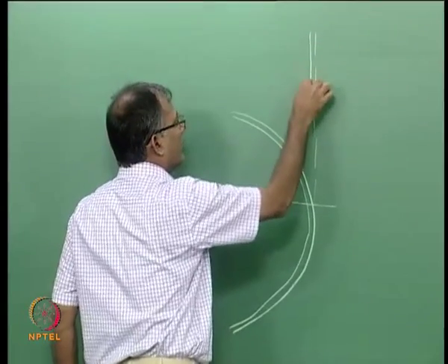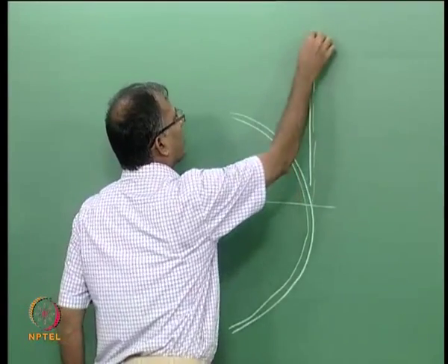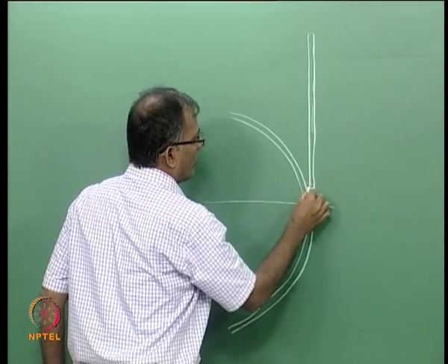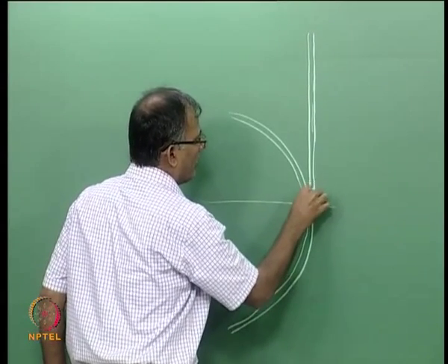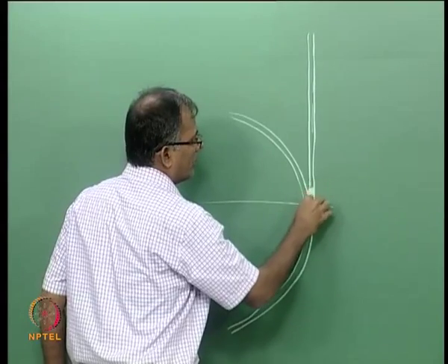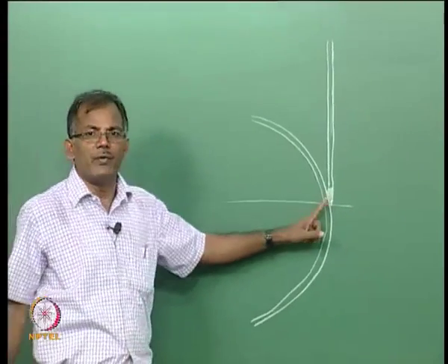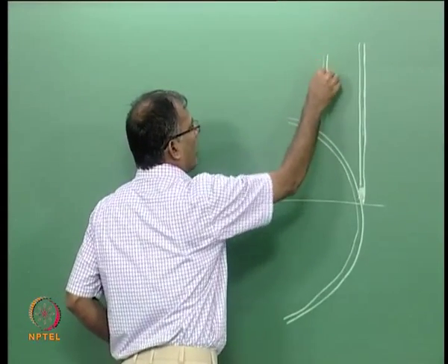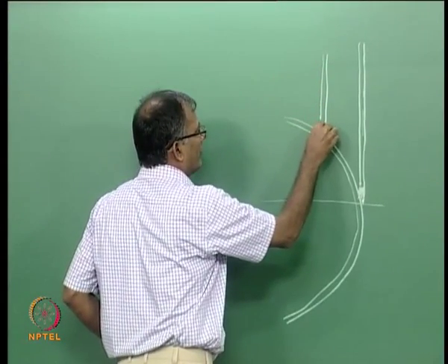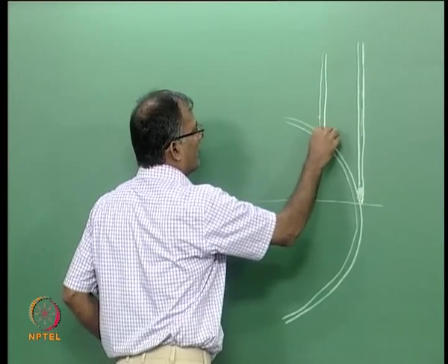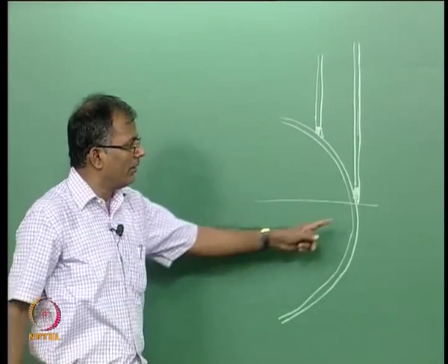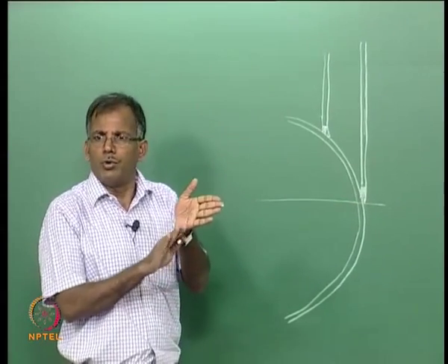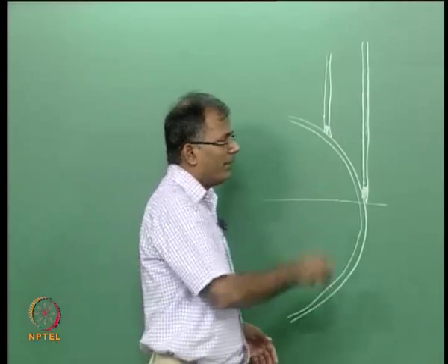So, if you take a plate like this, now you see here this welding, hope all of you can see this welding becomes very, very difficult, whereas if that same thing diameter is smaller, you can weld it properly here, whereas here this is a singular point where the surfaces of the brace and the chord are almost matching.